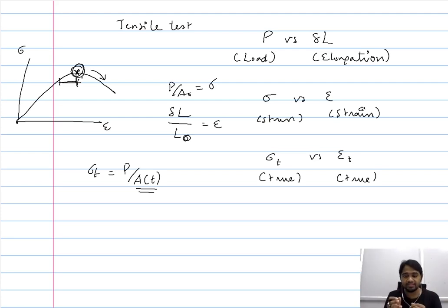And the other reason is because, like we saw here, for plotting the true stress strain curve, you need to calculate the instantaneous area at every given moment, and that requires a sophisticated set of machines. Therefore, the cost of tensile testing proportionately increases when you want to represent your results directly in true stress strain curves.